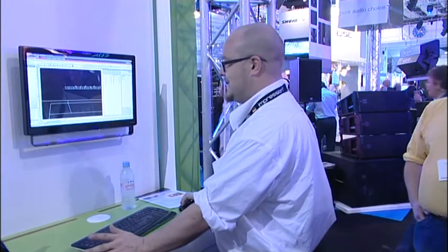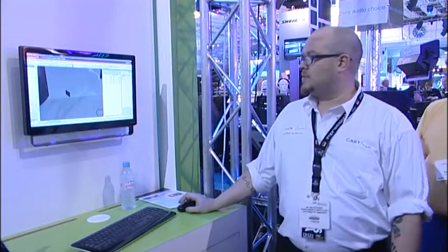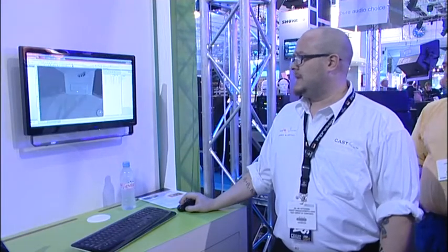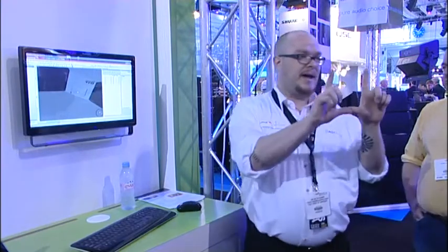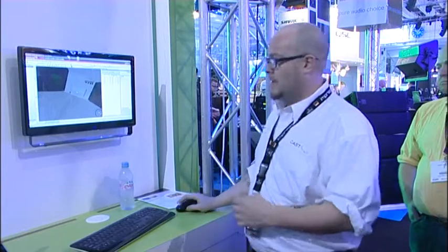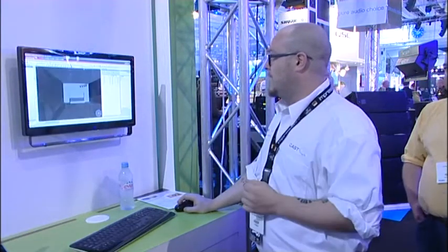So, as crazy as that is, one thing that we've added into Wysiwyg is the ability now to tilt the camera, to roll left and right on the camera. This is a tool that we can also lock out because, you know, if you're doing broadcast, it's always zero. We're always moving around trying to keep that jib right at the angle level of zero. Okay, I'm going to reset my directions here. So we've had a dimension of movement we call 6D, 6 degrees of freedom. Now you have all roll, pitch, yaw, X, Y, and Z right at your control anytime you need it.